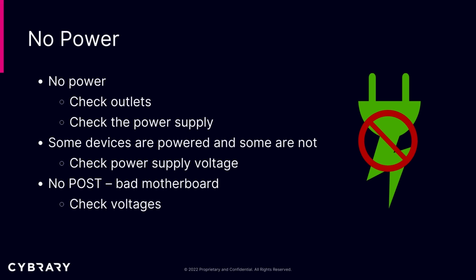There could be a problem with that power outlet. You may want to plug into a different outlet. If there is power in that outlet, then check the power supply on the device. If it's a power supply that has a power indicator light, and that indicator light is not on, you know that there may be a problem with the power supply. That power supply could be issuing some type of humming or noise.